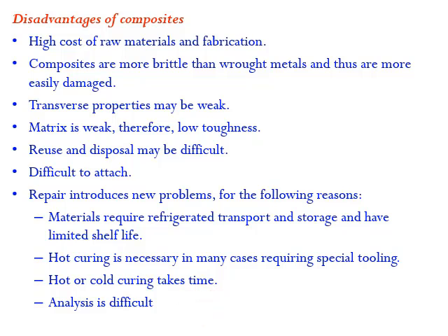Analysis is difficult. Whenever we process these composite materials, the curing time and processing are difficult. Many processes are not automated and not continuous. We need to wait till one product is completely processed, then go for the second process. So those are the disadvantages we normally get in composite materials.